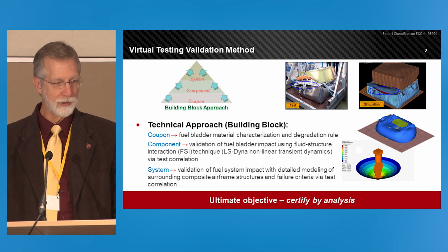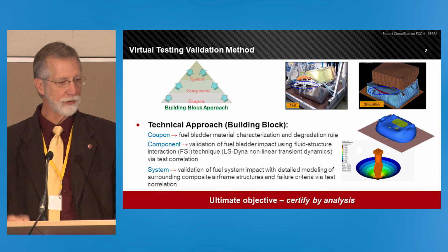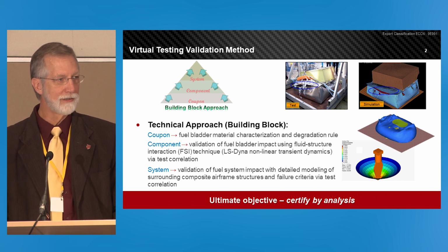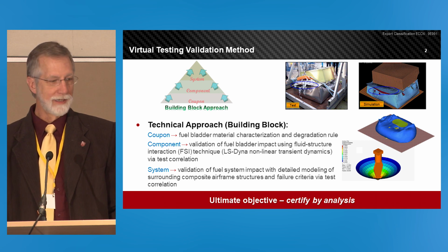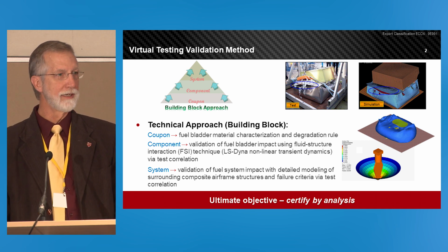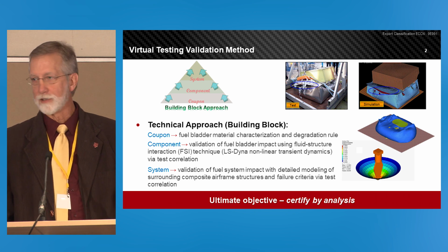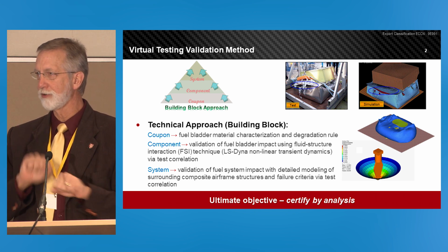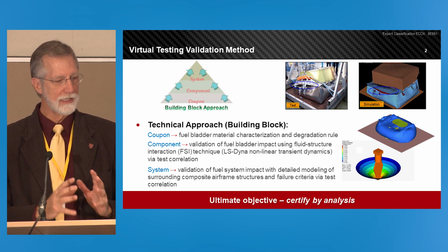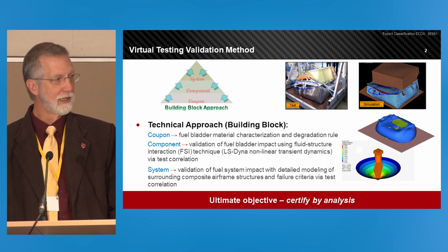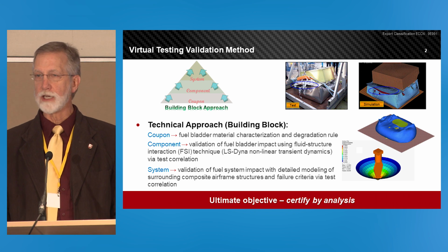Here I've shown the puncture test with a screwdriver poking through the finite element model. This is an LS-DYNA model. You develop the puncture capability, the tensile stress, the trouser tear, and so on. All of those individual tests develop the material characteristics. Then you build those together and do a component test.